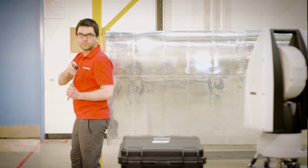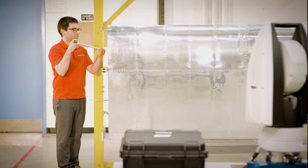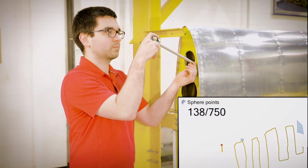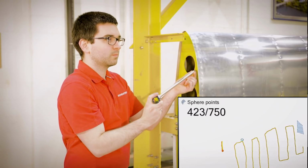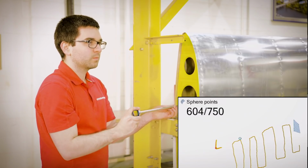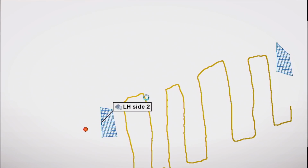For those who are not familiar with the sphere fit bar, the operator holds the tip stationary and moves the reflector about that point to generate a spherical point cloud. At this point, the measurement script takes over and fits a sphere to the spherical point cloud. And the center point is converted to a probe data point. As a result, the final plane is effectively probed and compatible with all of our standard analysis tools.